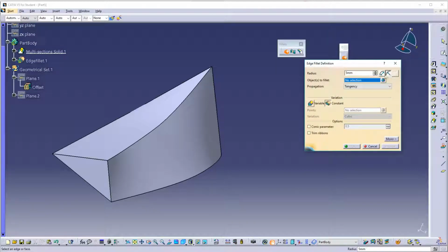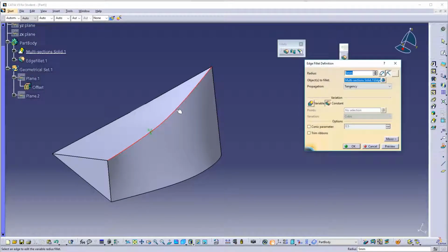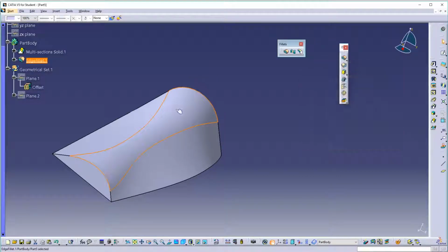And we're on the regular radius option, and let's pick this radius and let's put a value in of, say, 20. You know what, let's beef that up a little bit. We'll double click it and we'll make it 40. Okay, now that's a pretty interesting fillet, but it's not normally what they consider a good looking fillet in the automotive world from an aesthetic standpoint.